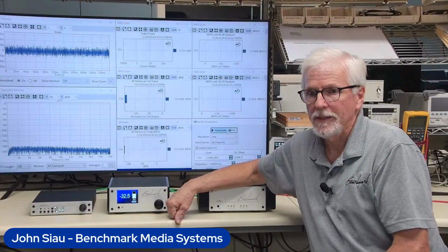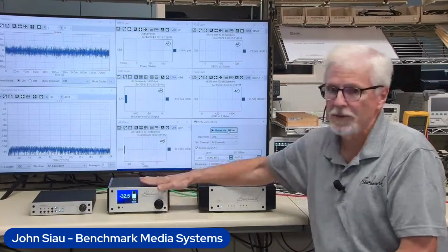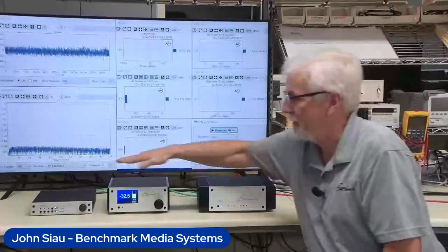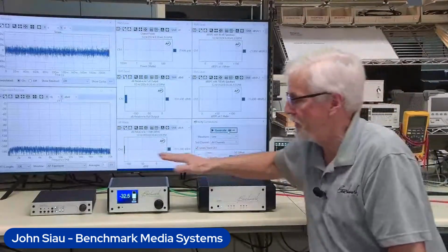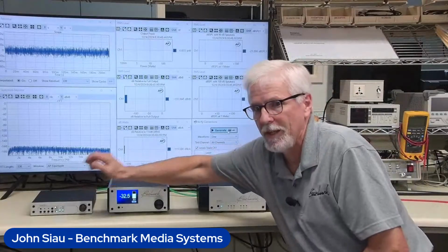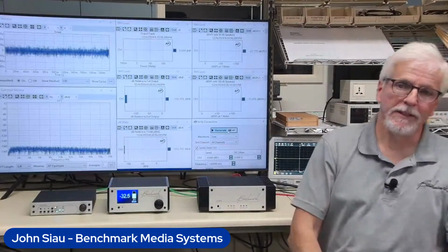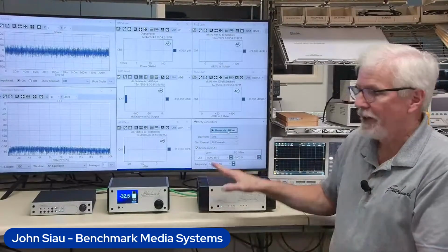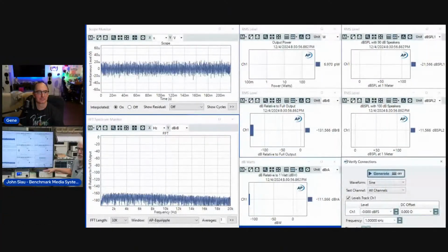Oh, interesting. Okay. Yeah, so you've got to be maybe 12 dB better. You see, we have a 10 dB difference between the signal to noise ratio of the power amplifier and the DAC. That's not accidental. That was the design goal, to be able to build a power amplifier that would deliver the full performance of the DAC3 converter.